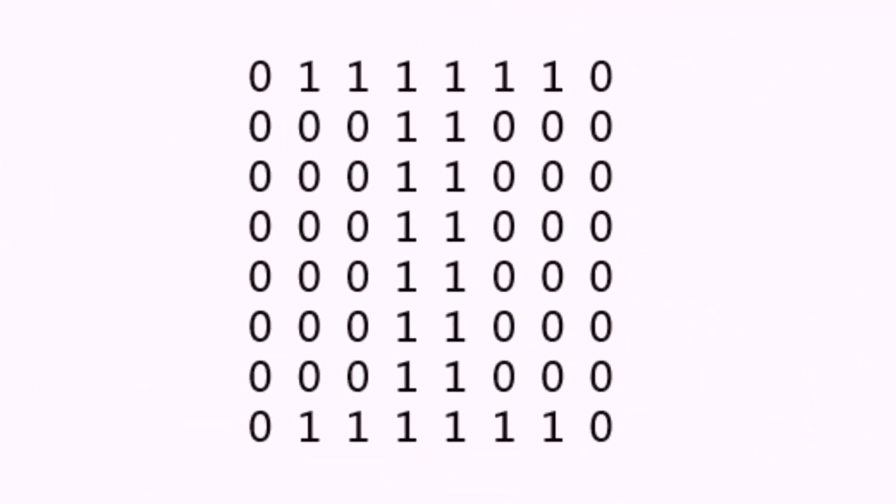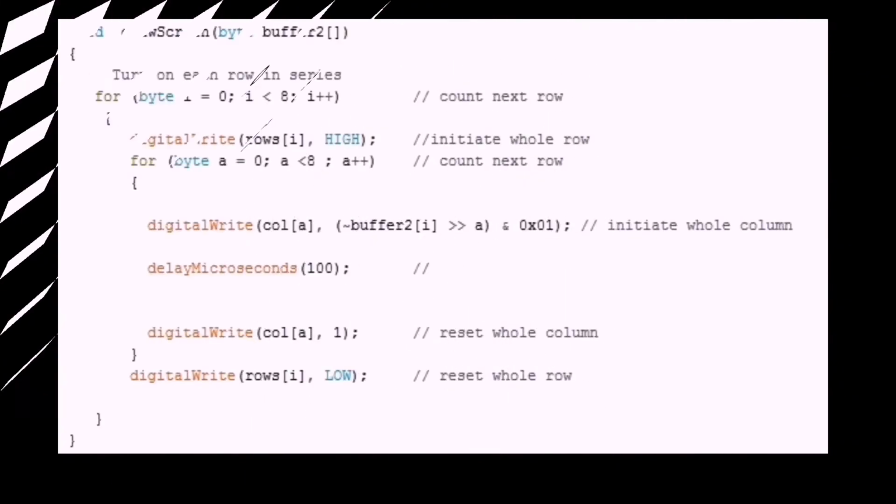Consider the simple example of an 8x8 matrix where we are required to display the letter I of the alphabet on the LED array. In this case of the 8x8 matrix, we will give 1s in the positions where we should light up the LED so that the final output will become the letter I. And the positions at which the value is 0, the LEDs will remain dim.